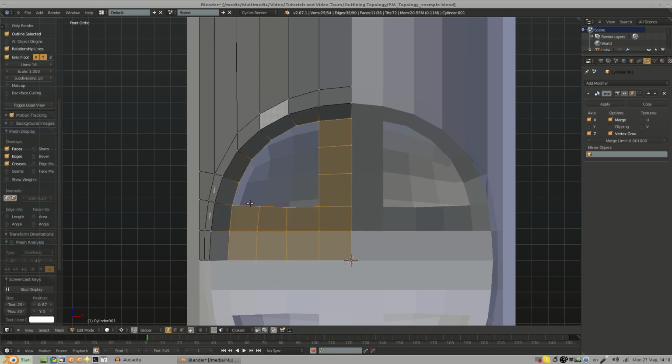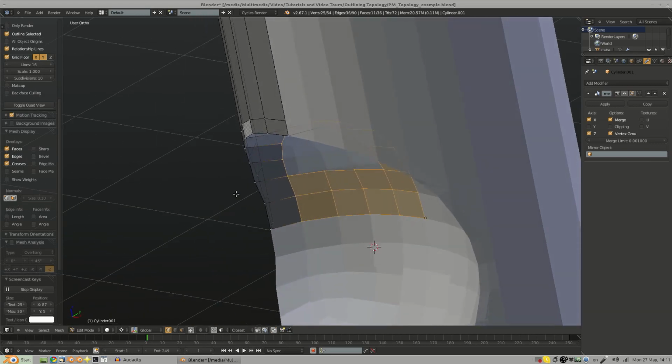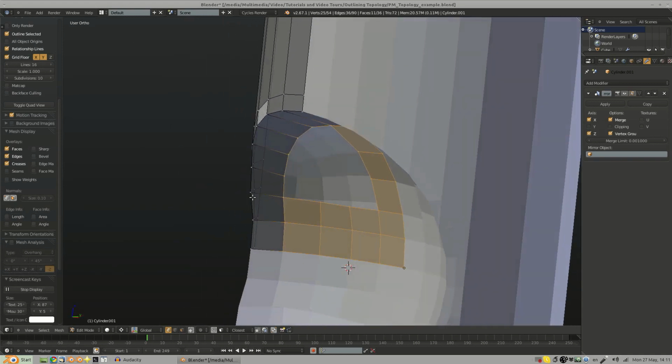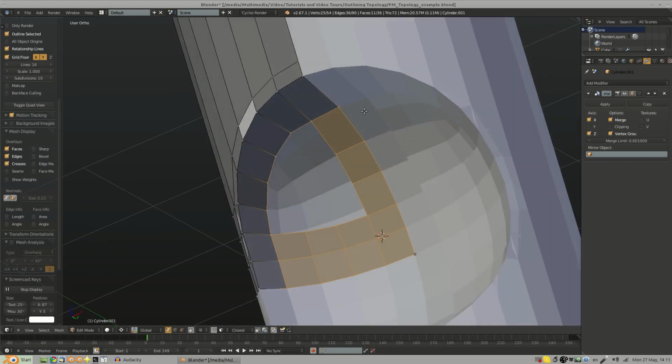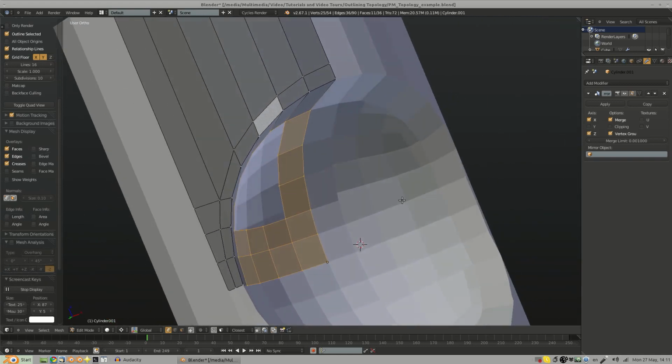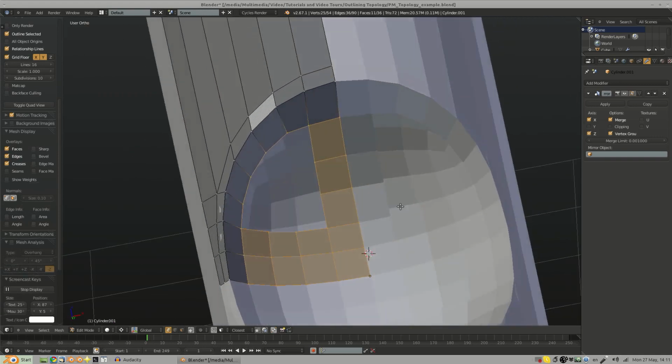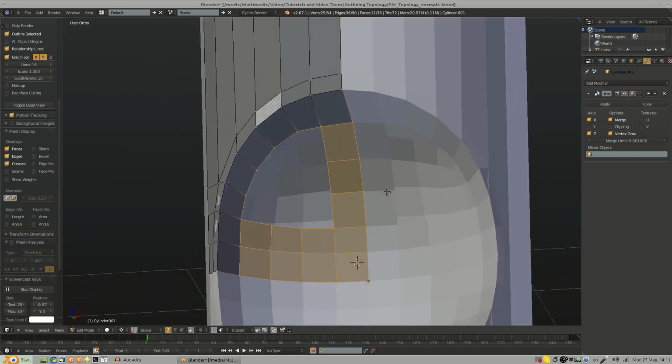And I'm going to press G. Now I'm moving my pen away so I can use my mouse so it doesn't move. Press G, press Control to snap, and confirm. So what that did is it basically shrink wrapped the topology, or these faces here, onto the surface behind it. And that is pretty much exactly what we want to do.